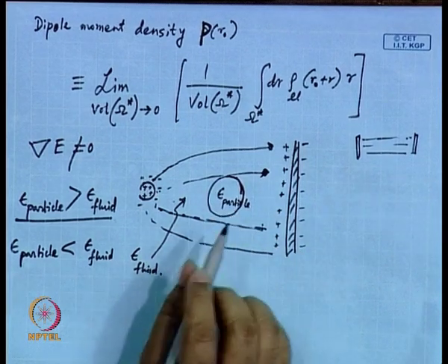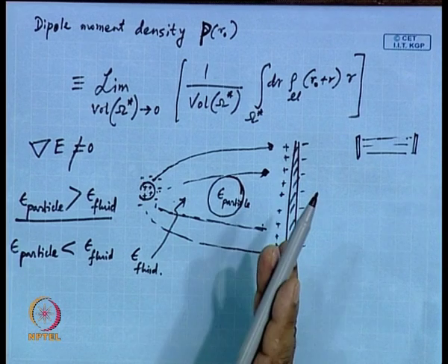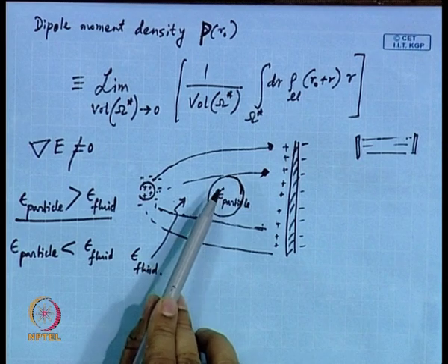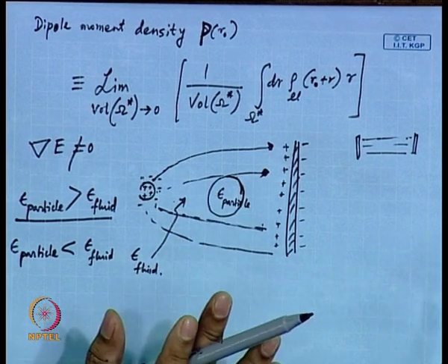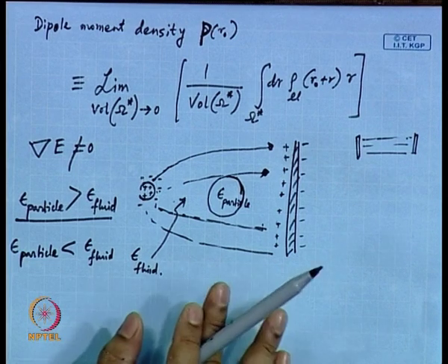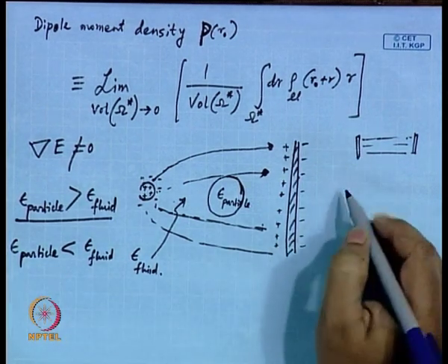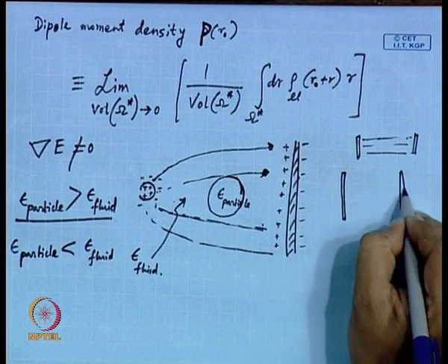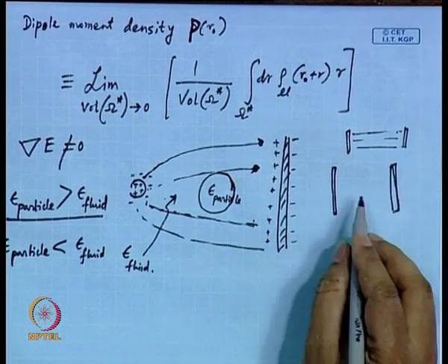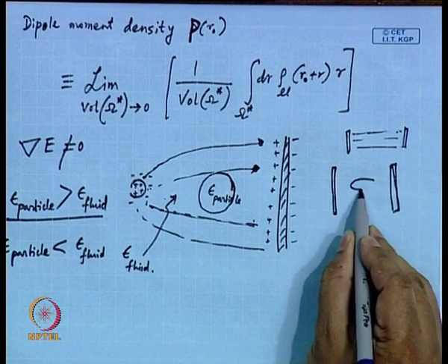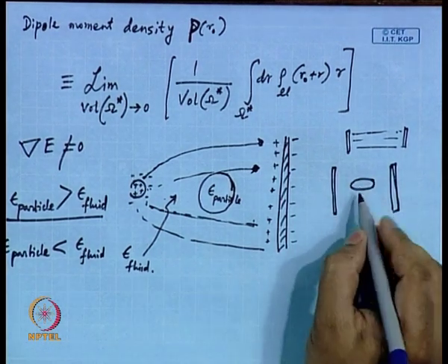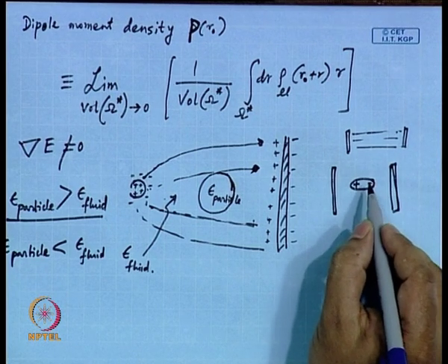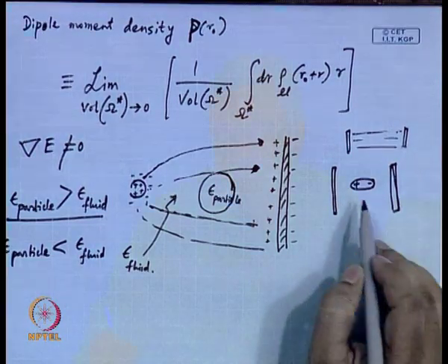There would be induced polarization that we have been talking about, this electric dipole moment, etc. So, there would be charges on the particle, net charge is 0, but on the surface there would be plus charges and minus charges. Think of what happens in a capacitor. If you have two electrodes and a dielectric particle present, what you will find is that, say, plus and minus, the charges will align themselves such that it remains this way.